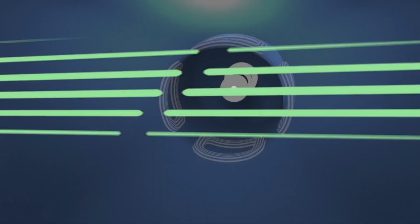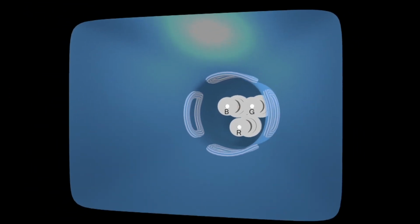But electrons themselves don't look like much. In order to make them visible, the screen was covered in a pattern of phosphor dots, which lit up when bombarded by the electrons, then dimmed back down on their own. And this was an issue. All this glowing and dimming had to happen instantly, over and over, at a constant frame rate, as high as 30 per second. You couldn't use phosphors that glow longer than a frame, because then the next frame couldn't be drawn in time. But when they dim fast, as every consecutive line of the frame gets drawn, the gap before the next one is too long for persistence of vision to handle, which in real time means flicker!